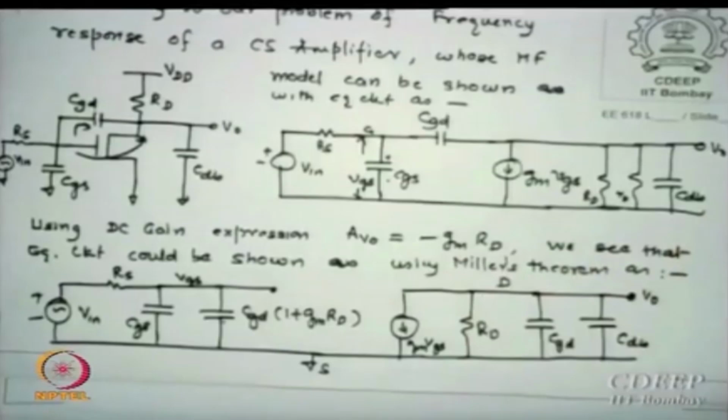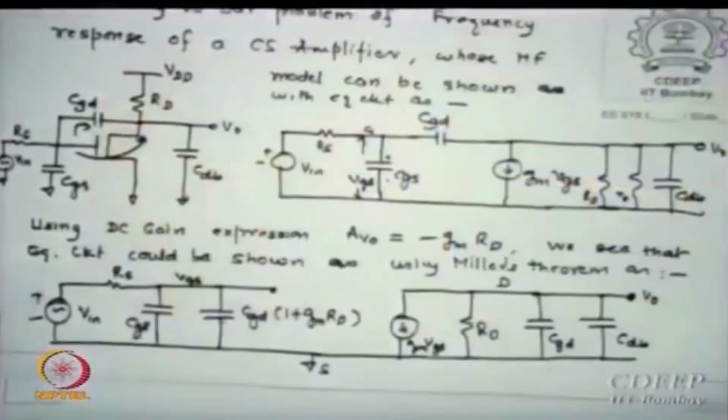So that is why when you calculate poles, the input of the next stage must be used as the output load for you, because in real life this is what it is going to see. Is that point clear? So at that time if CL is very large, the output pole becomes a very small frequency and that may become dominant. If CL is smaller or comparable to these values, then probably this may still dominate. But in many cases, if CLs are actually put, that may become dominant.